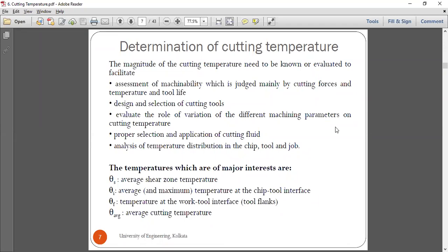As you have heard, while machining cast iron using a high-speed steel tool, HSS tool, we do not require any liquid lubricant or cutting fluid from outside. What is the reason behind this? Because in cast iron, graphite is already there in the form of solid lubricant.